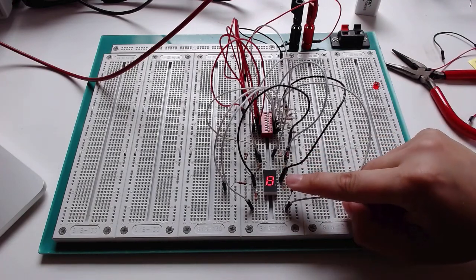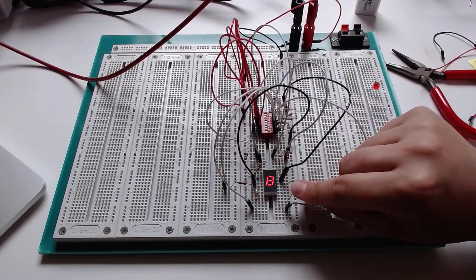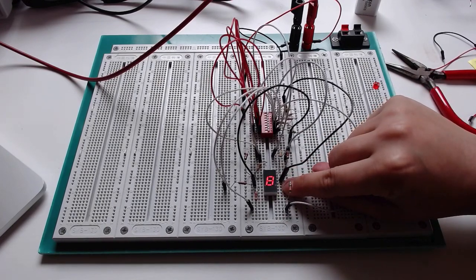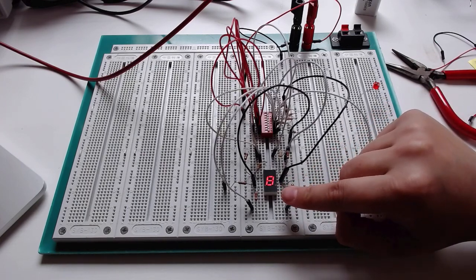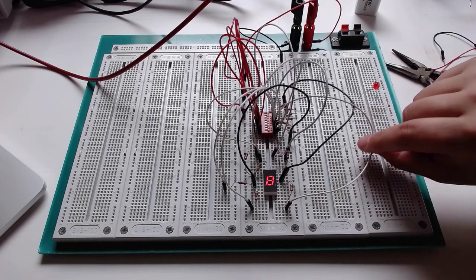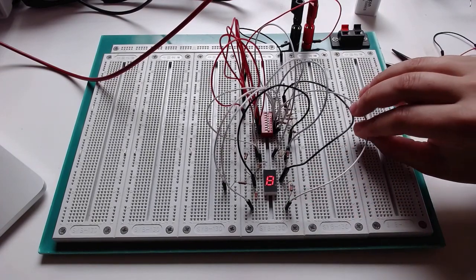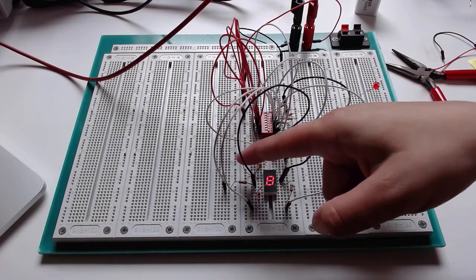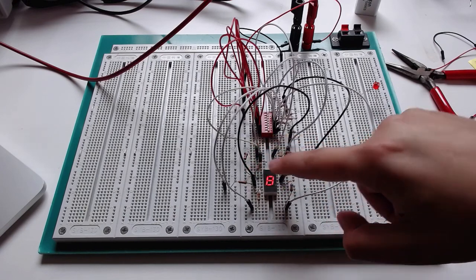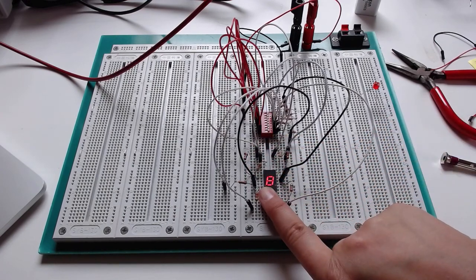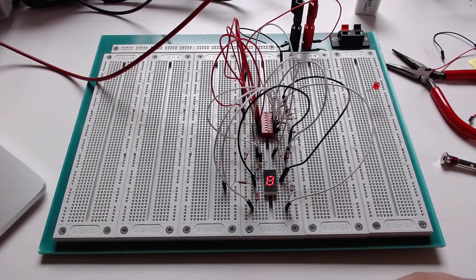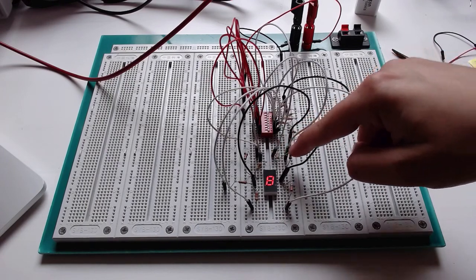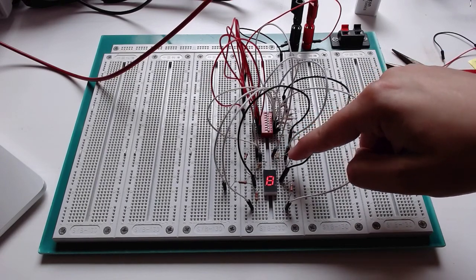What you might notice is that I've taken every single one of these resistors and I've pulled the leg that's not connected to the anode to a different unused row on the breadboard and then connected that other end of the resistor to my dip switch. So it takes a lot of real estate to connect a 7-segment display because every single one of these resistors needs to go between the segment anode and a new spot on the board, someplace different. Okay, so I've had to take every single one of them and put the other end of the resistor to a new spot on the board.